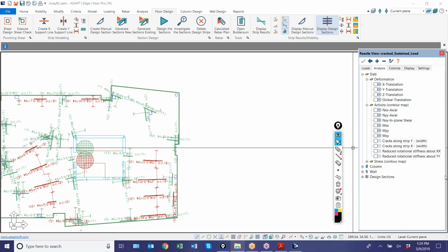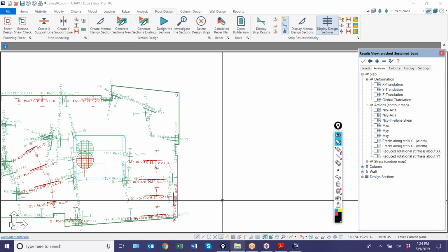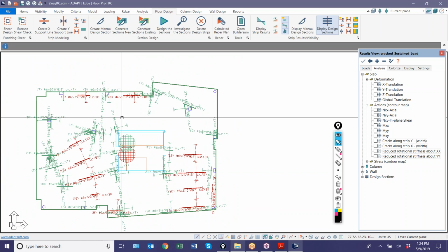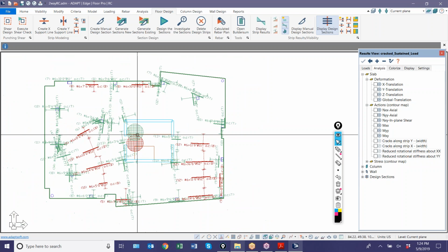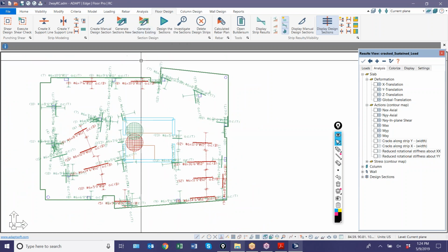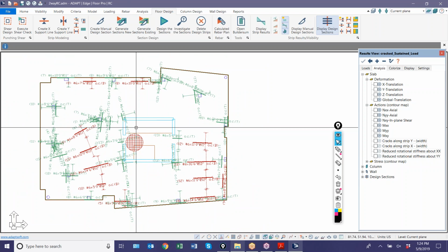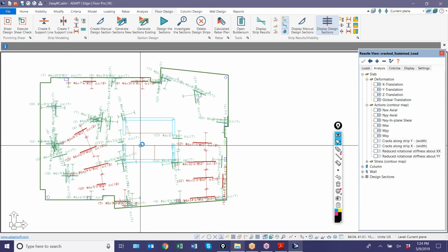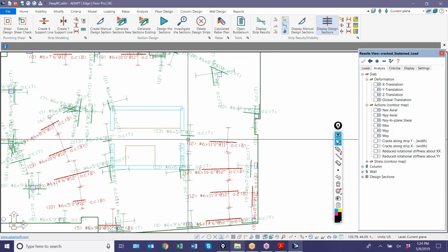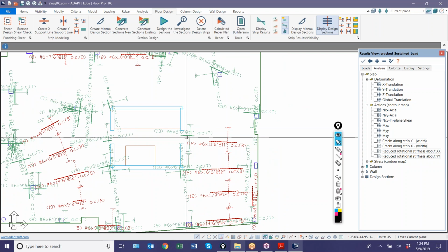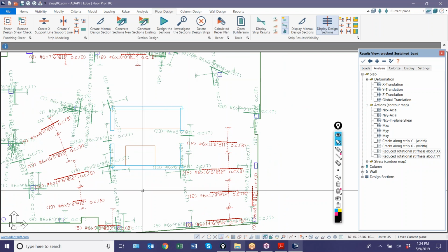The question is, even though we specified the opening and added splitters around the opening, rebar has been designed in that area, and can we avoid mesh reinforcement at the opening? Yeah, you can avoid mesh reinforcement in the opening if you don't use the wizard. And some of this rebar that creeps into here is really just based on some extension parameters in our algorithm for generating the layout.